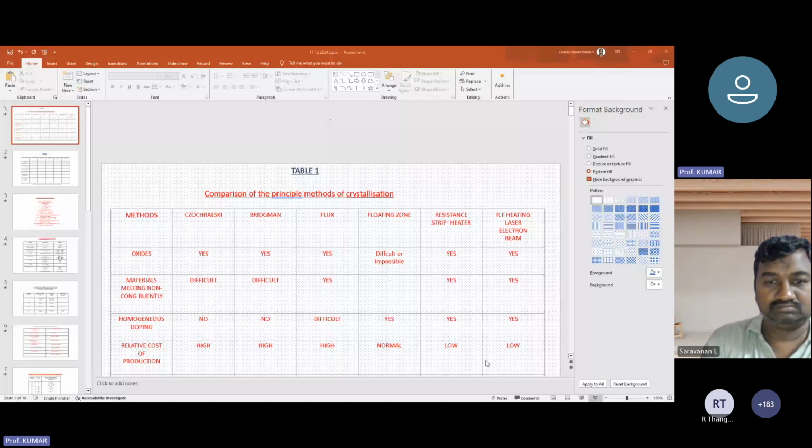As I said, one of the fundamental techniques used for understanding the properties of materials, in particular, let us say indium phosphide, which is a compound III-V semiconductor, is, as I told you, the room temperature Hall effect measurement, which is the most important. And you can see here, if I have tin or sulfur as the dopant, they will exhibit n-type characteristics.